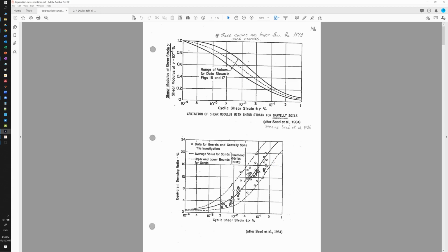You get some soils from California, some soils maybe from somewhere in the Midwest, and some soils even from Japan, and they put them together as the database. It is useful in a way that it is a good start, or you're working on a project that doesn't have the budget for site specific testing, which is extremely expensive, and not many labs in this world are able to run those resonant column tests for you.